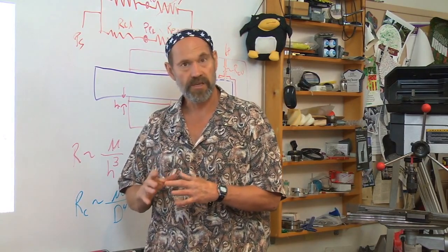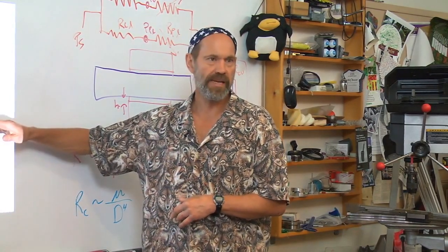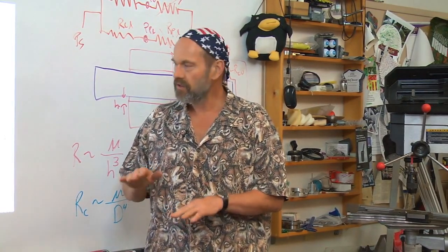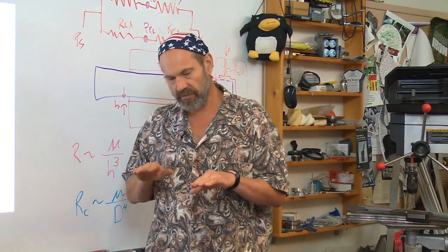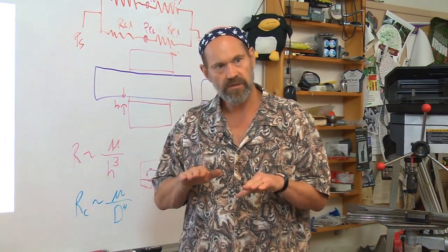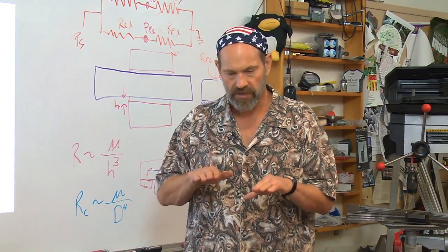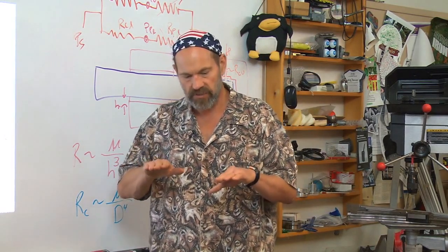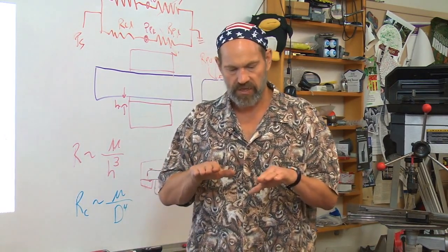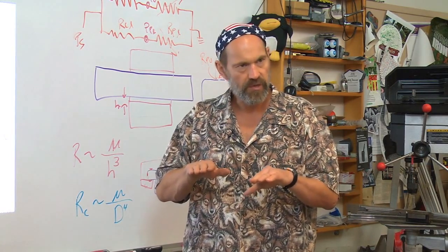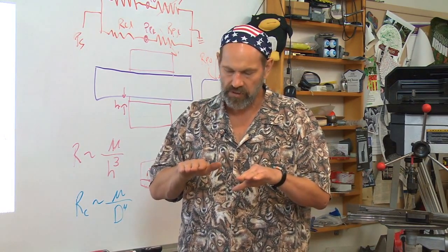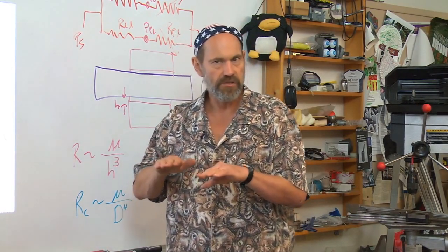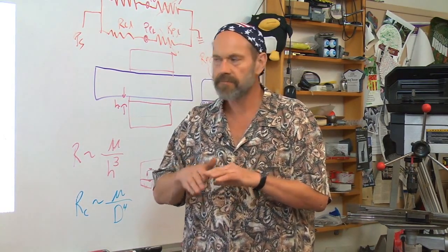Those stages are typically supported by magnetic bearings because they can not only be very fast, you can actually measure the position of the stage as it's moving using laser interferometers, feed that signal back into the machine controller that senses when the stage is moving not the way it should be, and magnetic bearings then servo, that means active control, the motion of the stage to eliminate parasitic error motions and get the highest of high precision.